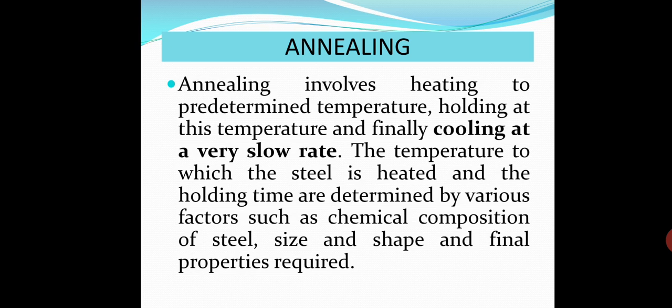So, different types of heat treatment. Heat treatment has three phases. One is heating, second is holding, third is cooling. So heating to which temperature? Then holding for how much time? And cooling at what rate?